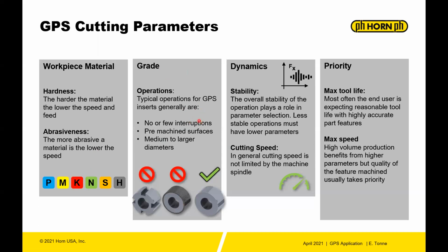So interrupted cuts aren't really thought of when developing grooving or part-off systems. It's mainly thought of as a continuous process. So keep that in mind. Try to avoid interruptions, try to avoid scale or other things, clean those off with another tool and then use your groover as it's intended.